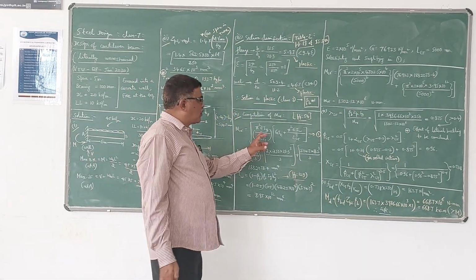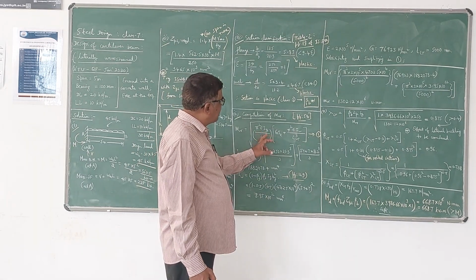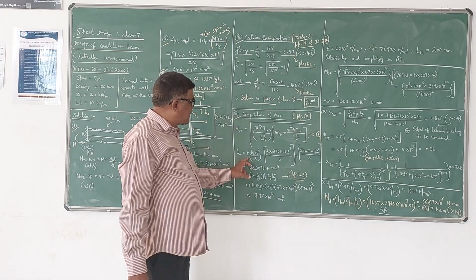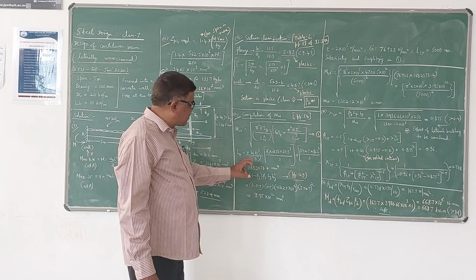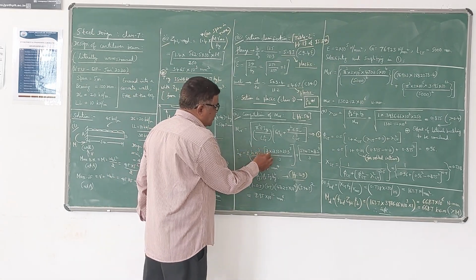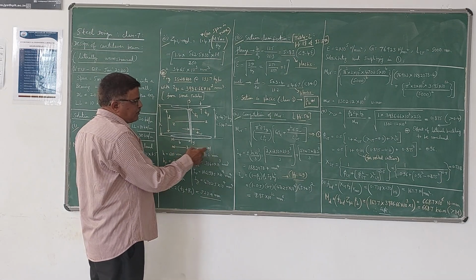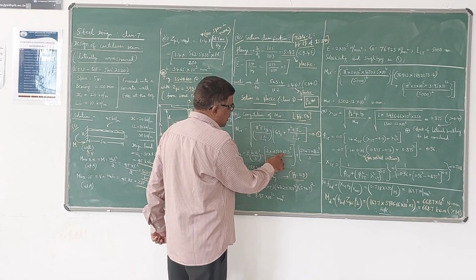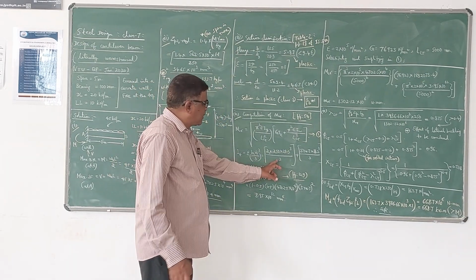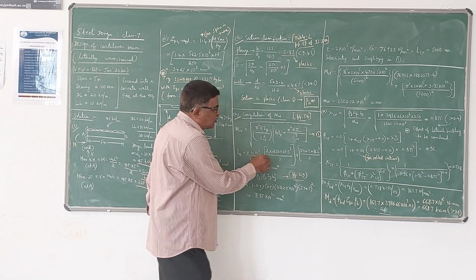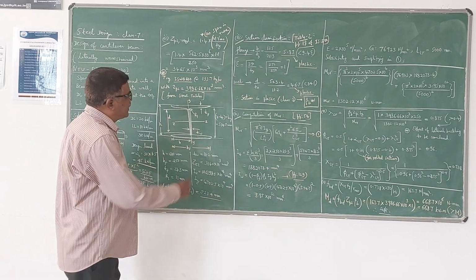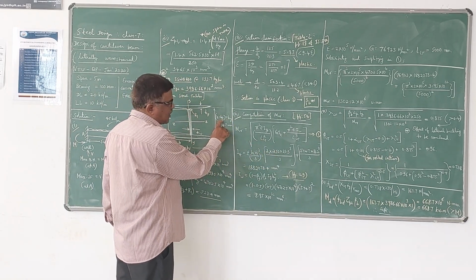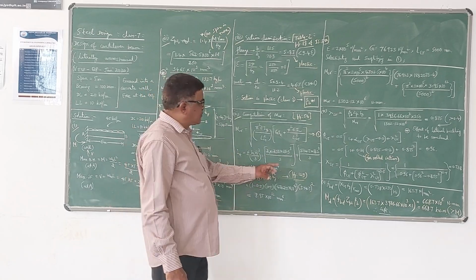So we require two more parameters, that is we require this It and Iw. It is called the torsion constant, which is given by sigma bi ti cubed by 3 for that particular section. There are two flanges here, so 2 times the flange breadth bf, which is 250, into tf, which is 21.3, cubed, divided by 3. Because there are 2 flanges, we multiply by 2. Plus for the web portion, we take h minus tf as bi.